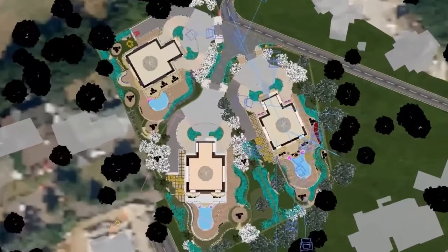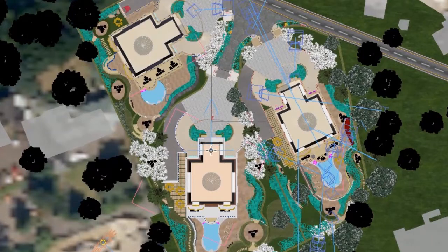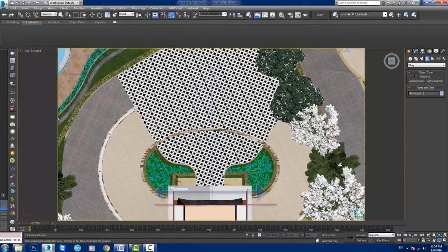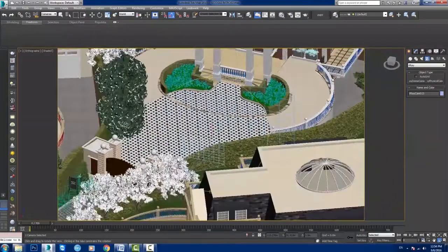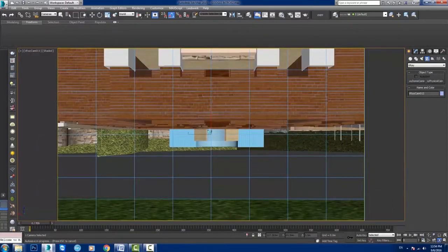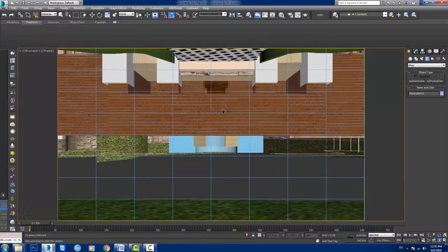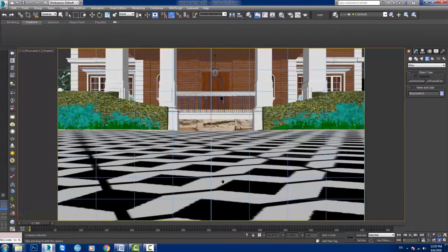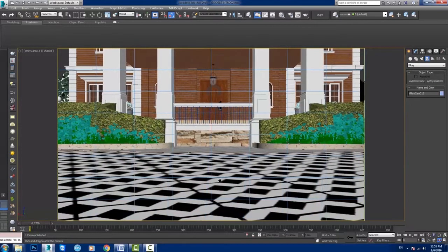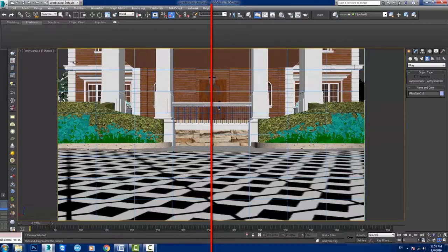Let's start by creating a V-Ray physical camera right here and try to position it as parallel as we can to that elevation. So now we have a camera that is parallel to the elevation of the villa. Now the camera has been created at the 0 level in Z position. So if we press C while it is still selected, we will view what the camera is shooting. Now the camera at the 0 level is basically shooting under the building. We will use our middle mouse button to pan and move it upwards, and that will be the first frame of our camera movement.